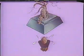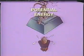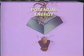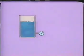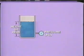Pressure, on the other hand, is a form of potential energy. The potential energy of a substance is a result of its position. This 2-ton block has the potential of doing quite a bit of damage, since it is positioned above the ground. We say the block has potential energy. A column of water stored in a tank also has potential energy. We can measure this potential energy in terms of pressure, or in units of height or head.